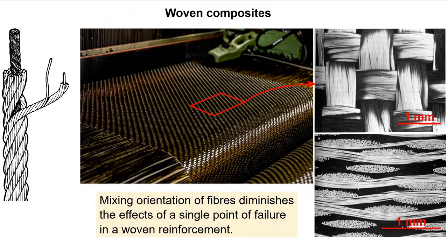What is potentially different is the length scale of the textile that makes up your jumper versus the length scale of, say, carbon fiber reinforced polymers, as I'm depicting on the right. The cross-sectional diameter of each fiber is around 10 microns, and these are bundled and woven together as depicted by the cross-sectional view on the bottom right. This is one pattern of many. In the same way as there are many weaves of cloth, there are many for fiber reinforced polymers. The arrangement of the weave may create more reinforcement in any given direction versus another, affecting final properties.